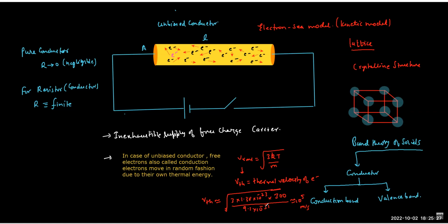If you imagine a nanometer dimension, an electron will survive in that nanometer radius sphere, and it is going to live there because of the collisions from all directions. So symmetrically, all electrons will distribute in a way that you won't see a net motion. The motion is not there actually. So this is called localized motion. Everyone is moving locally, but there is no bulk transmission. There is no diffusion process taking place.